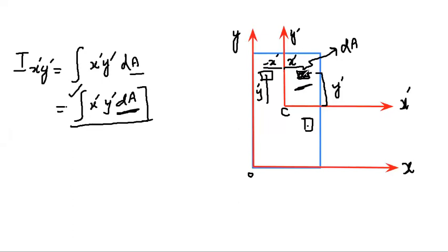On its left hand side we will have one more area element dA. As you integrate, this area element has to traverse through the entire area of the plane. As this area element reaches here, by the process of integration, what happens? Your x coordinate becomes negative, your y coordinate is positive. So the product of inertia of this area element is cancelled by the product of inertia of the other area element, because these two area elements are symmetric to each other.